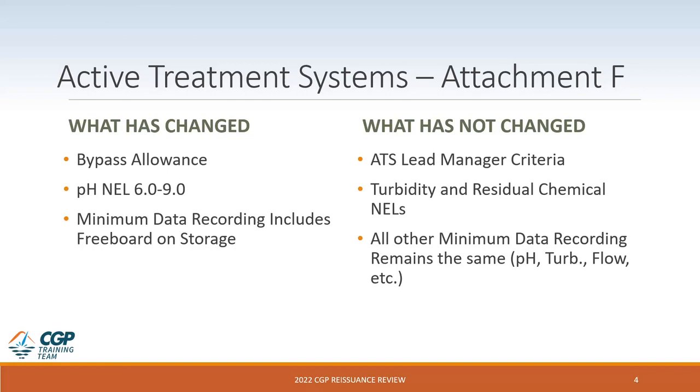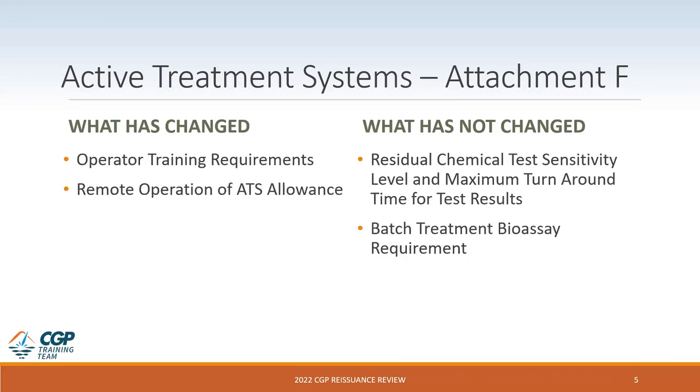And then what has not changed? The ATS manager criteria has not changed. The turbidity and the residual chemical NELs have not changed. We've just added the pH NEL. And then, like we talked about, the turbidity, flow, pH, all those minimum recording parameters remain the same. We've just added the freeboard parameter.